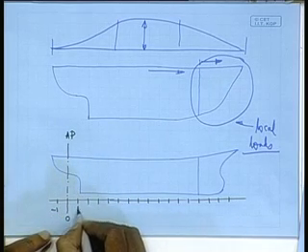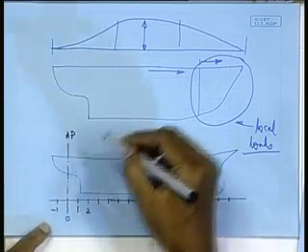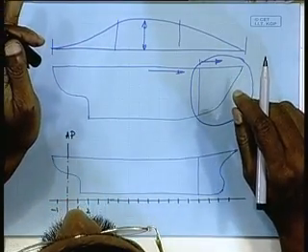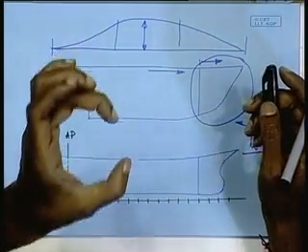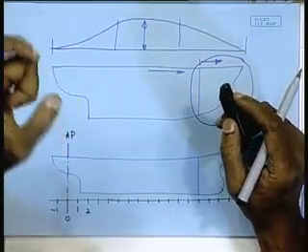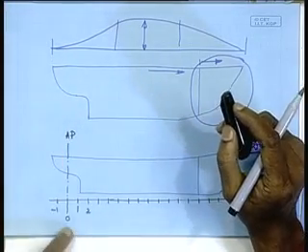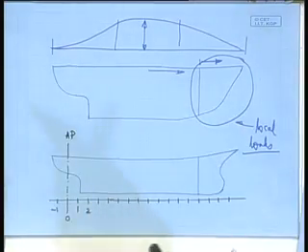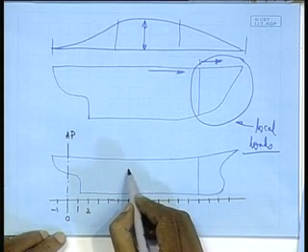Minus 1, this is 1, 2 and so on, right. And the outer perpendicular is the location where you have the center line of the rudder stock. There is a rudder for maneuvering; the vertical axis of that shaft of the rudder is called the rudder stock. Anyway, I coincide my 0th frame location with the outer perpendicular. Then I have 1, 2, 3, etc. So that gives me, then, I can define any plate anywhere, right.